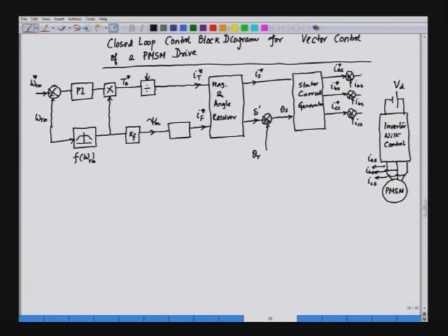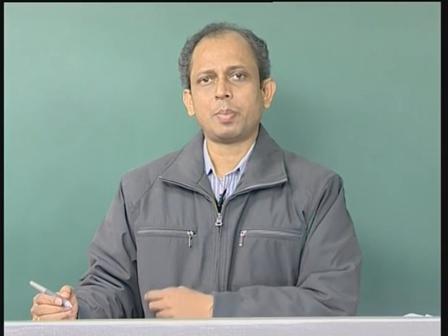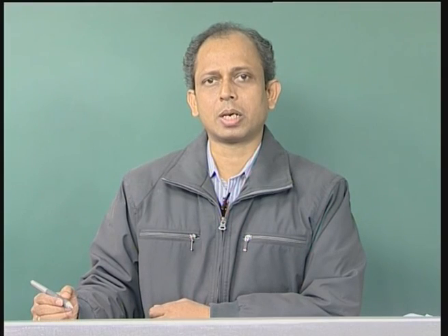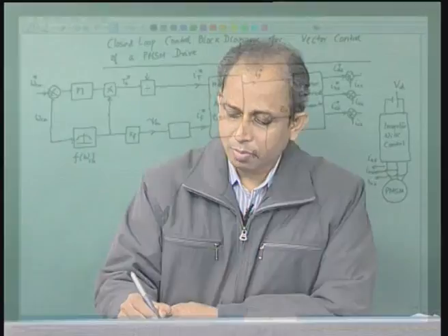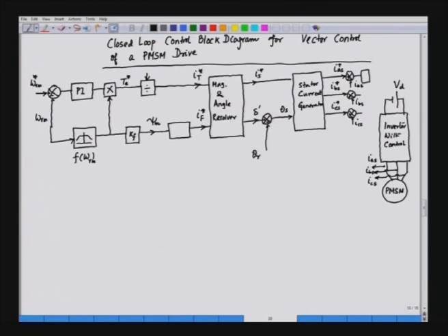and this comparator will be giving us an error, and the error is processed through usually a hysteresis controller for control of the inverter. So, we can have a current control mechanism here, and one of the popular mechanisms of current control is hysteresis current control, in which we can have the hysteresis control after this comparator block. For the 3 phases, we can have 3 hysteresis controllers,